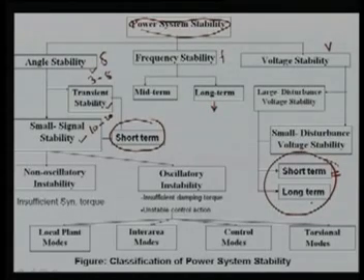In the long term, voltage stability involves the slower acting equipment such as tap changing transformers, thermostatically controlled loads, generator current limiters, etc. The study period of interest may extend to several or many minutes, and long term simulations are required for analysis of the system performance. The stability is usually determined by the resulting outage of equipment rather than the severity of the initial disturbance. Instability is due to the loss of long term equilibrium when the loads try to restore their power beyond the capability of the transmission network and connected generation. The post disturbance steady state operating point is small disturbance unstable, or there is a lack of attraction toward the stable post disturbance equilibrium.